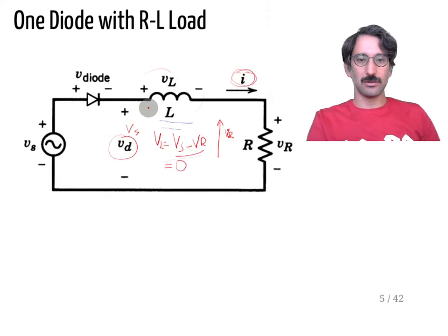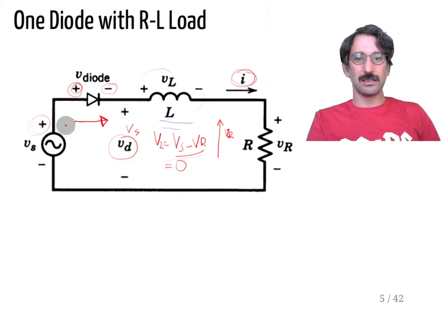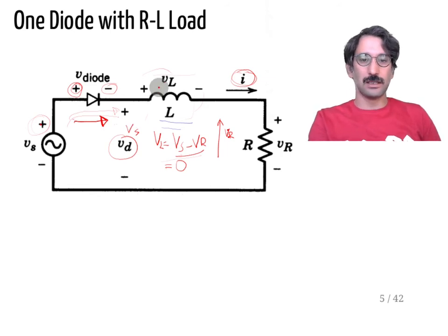Okay, so it's because there is non-zero inductor current and non-zero VL voltage. From that diode's perspective, it doesn't really look into the Vs voltage, it just looks at the polarity at that side and that side. So if there is still some voltage difference, it will still conduct, and if there is some current passing through here, it will still keep flowing. And as a general rule, remember, you cannot turn off the inductor current immediately. It will take some time to turn off the inductor current.